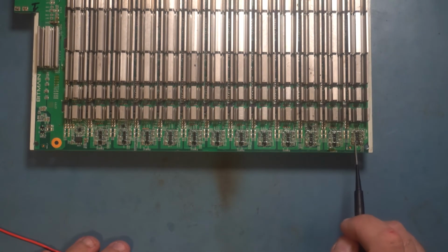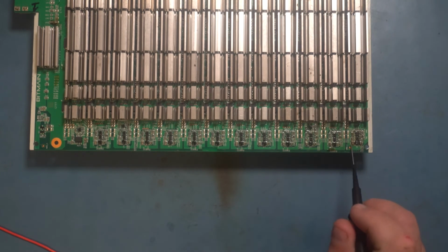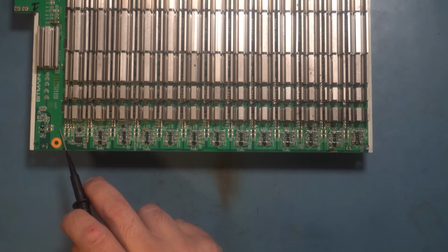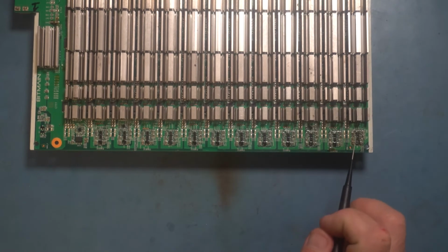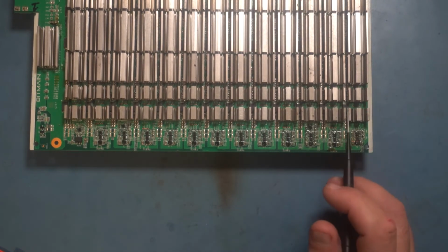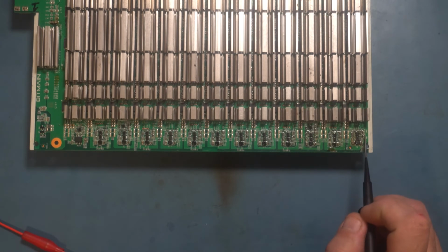Like if I were to take the input pin of the 1.8 volt LDO there and just connect it all the way to the 24 volts and then change the circuit accordingly, then I could take 24 volts, regulate it down to 1.8, and I would have a really strong 1.8 volt that's really, really solid.